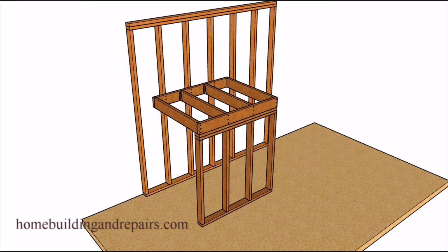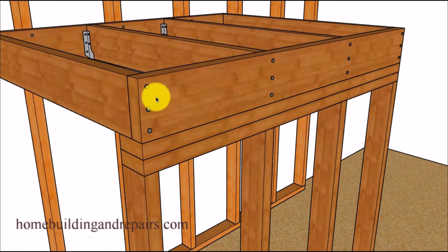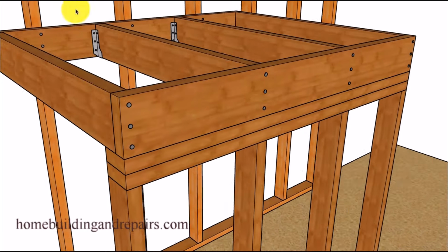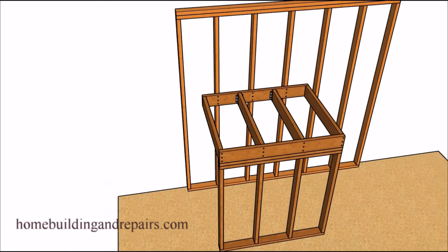And this is probably going to be the most common, and that will be where you have a rim joist and you're going to nail into the joist. And if you're using 1.5" construction standard lumber like we're using 2x6 here in the video, then you can probably get away with using 16D nails. And those nails will be used for everything except for the joist hangers most of the time.